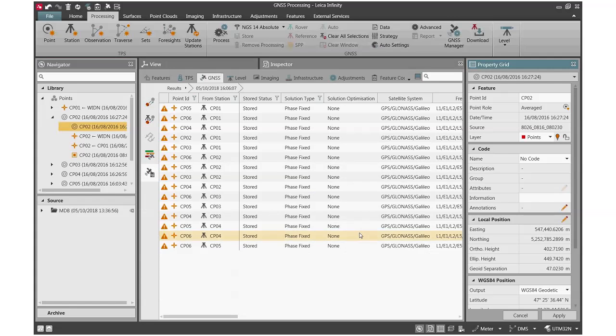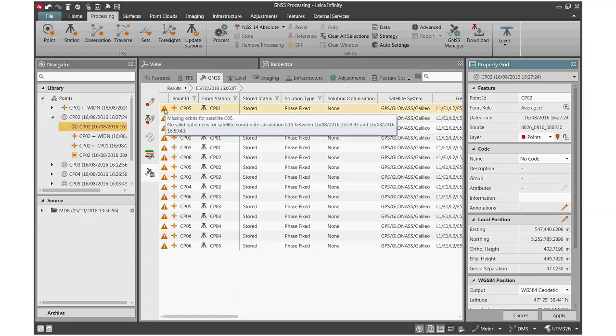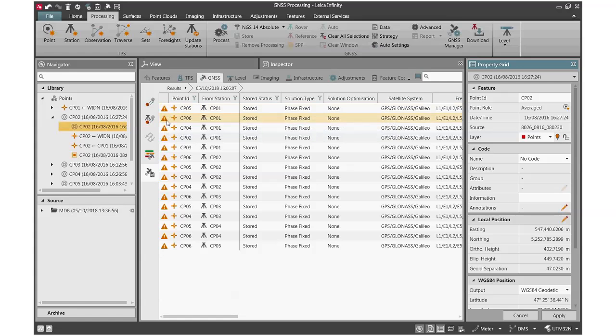Katie is just pointing out why the exclamation mark here does not go away. It's because the reference station we downloaded from does not have this navigation file, and that's why it failed. By right it should go away if that reference station has the so-called Beidou tracking. So we can see all is the Beidou. I'm sorry, but this is the fact.